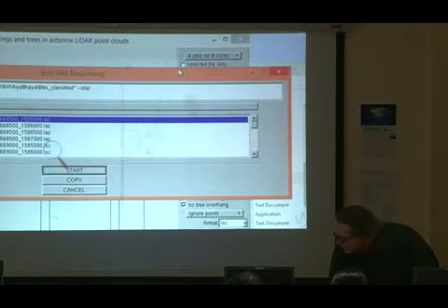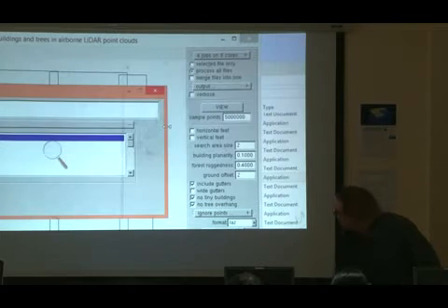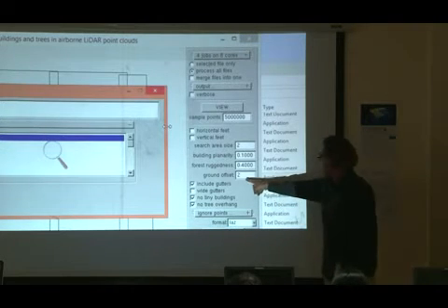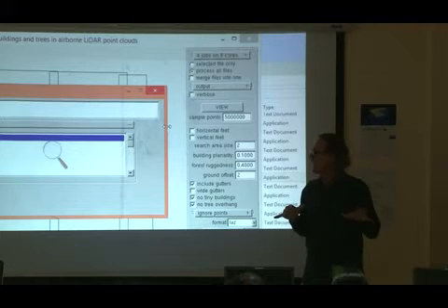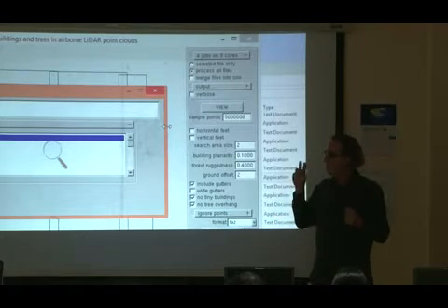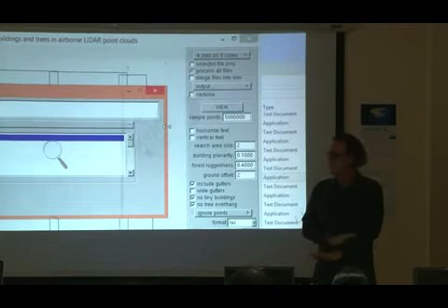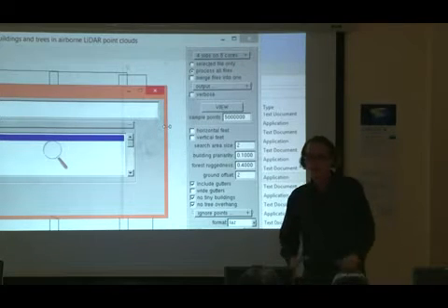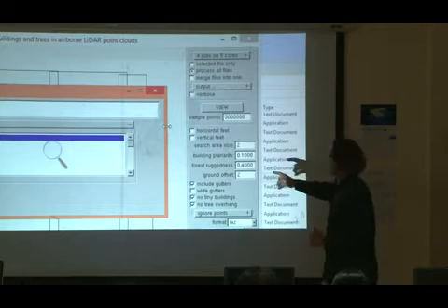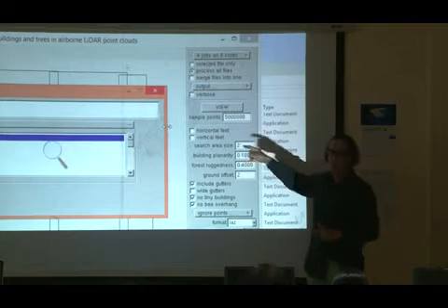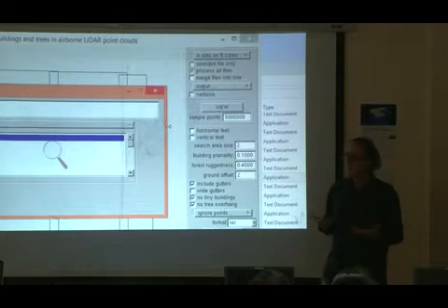If, for example, you wanted smaller buildings, the ground offset. It only looks at points which are 2 meters or higher. That's why it needs to know the height above ground. So everything else it just ignores. Now it looks at these points in a 2 by 2 meter area and looks at how planar the points are.